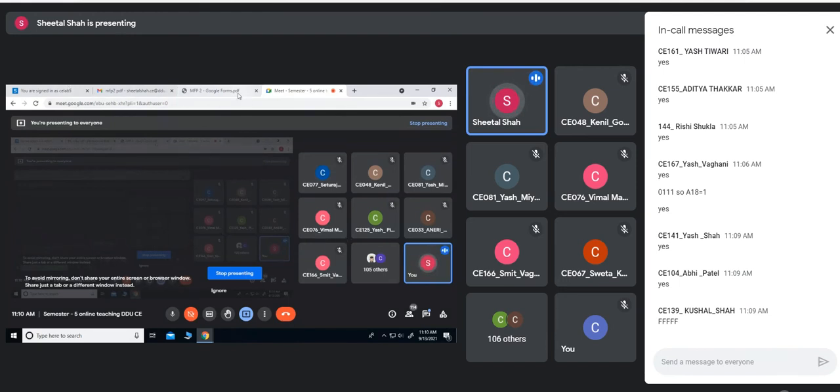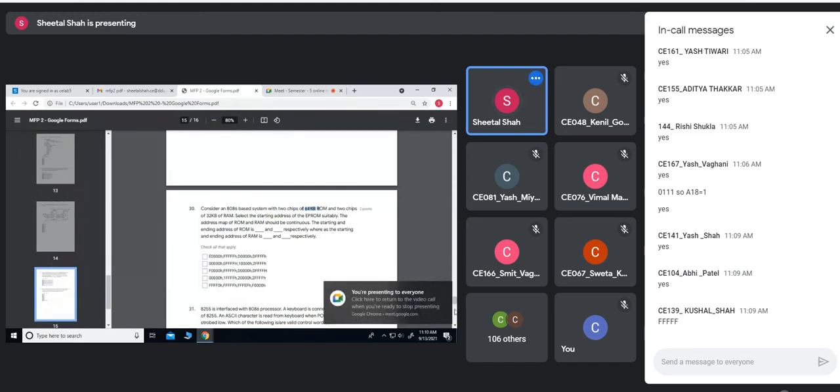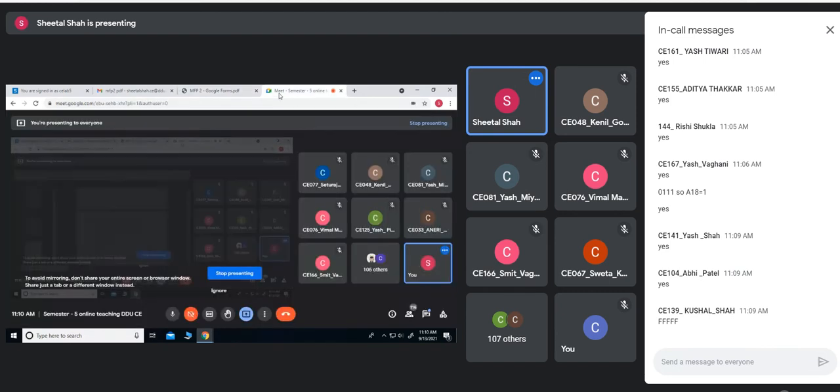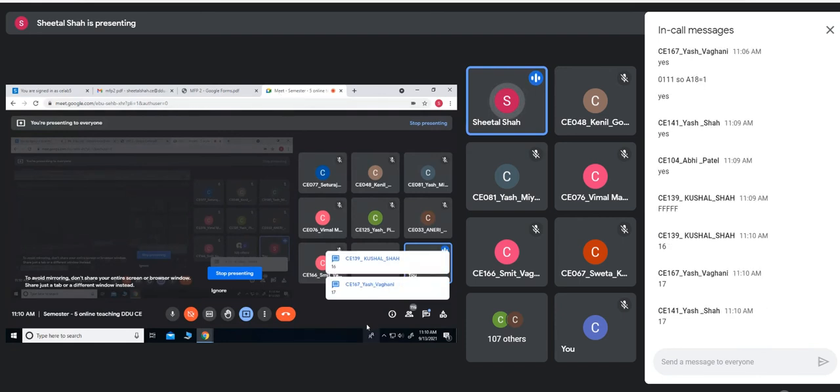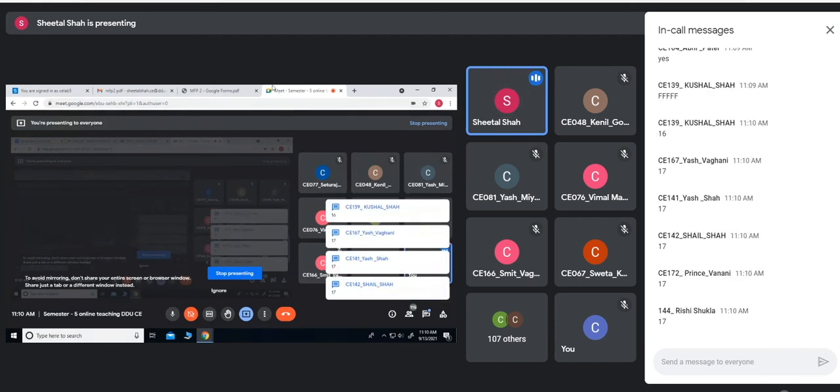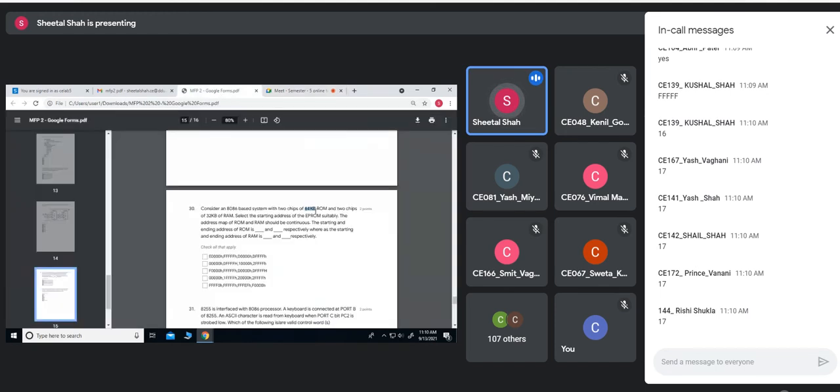If it is mentioned specifically, then you can use that address. But if it is asked to be chosen suitably, then you have to use FFFF0 as the ROM address. Followed? The size of the ROM is 128 kilobytes because there are 2 such chips. To address 128 kilobytes, how many bits would be required? 17 bits. Fine. So A0 to A16 are meant for addressing the ROM.